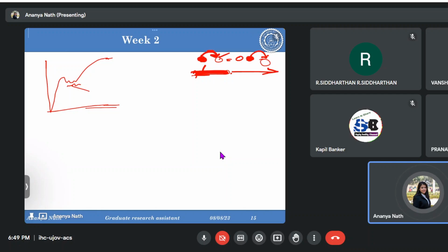But if we are talking about the energy between the dislocation and solute, which is given by U, which is A sine theta over R. We are denoting, if this is a slip plane, this is a solute atom present over here.